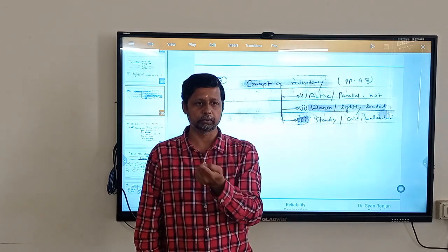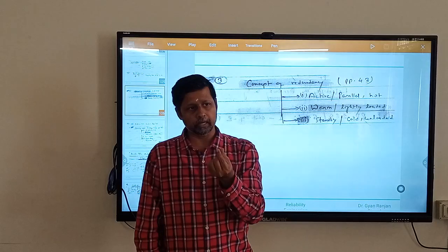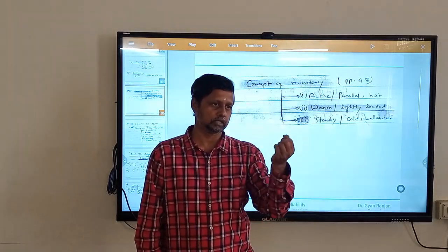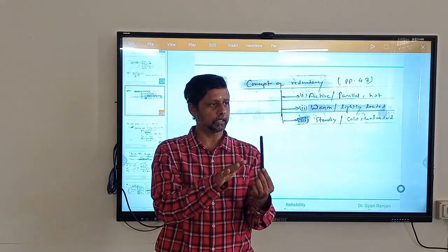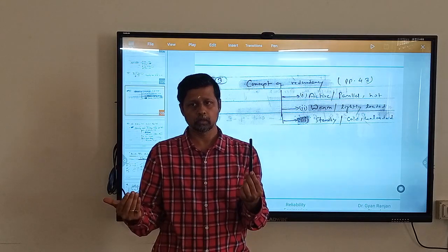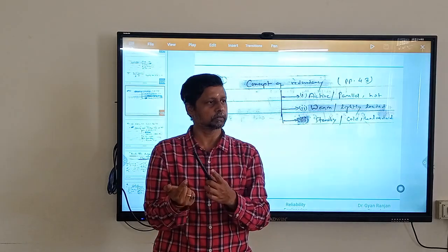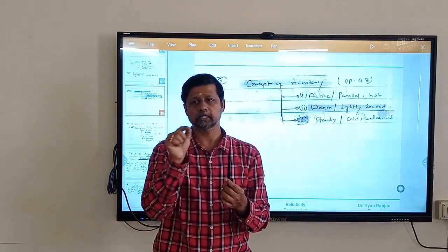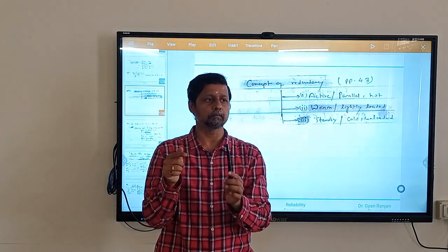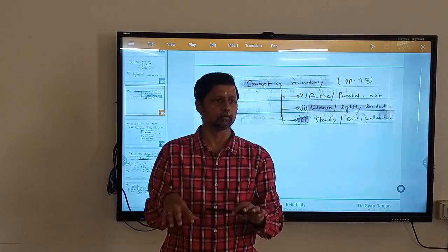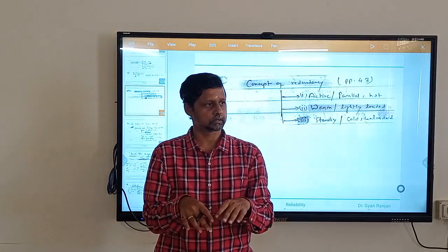That means if needed, you can repeat one more cycle within the sample itself. So in 2 microseconds, the last sample has been collected from 83B. That is the last point when 83B is fed. Now it's empty, so it has to switch to standby mode, and the standby one should take over in active mode. This transaction will also take some time. So 2 microseconds plus this swapping time, so that 83C comes into active mode. Everything should be done again within 5 microseconds.